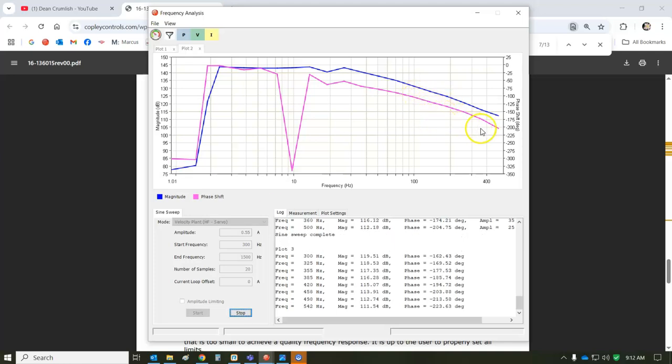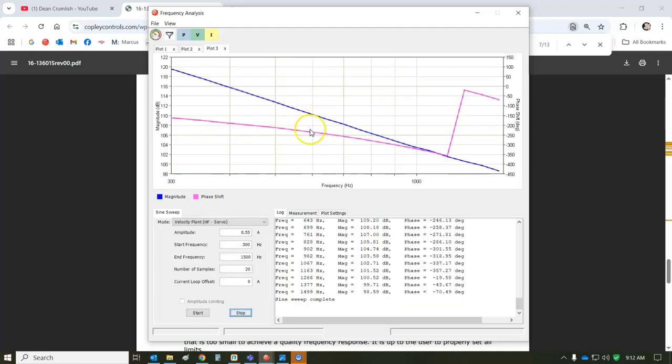So there must be a pole around 300 hertz. We know there's one in the velocity loop. I got some integral in there, so there's an integral break frequency that should carry my velocity out further. So that may be why I'm not rolling off. Well, it could be 20 dB per decade, so that does appear to be so. But this is the plant, velocity plant. Okay, so we can see the roll off and the phase shifting, and then this is just a wrap. It doesn't really jump up this way; it just continues down further on. It's just a way to plot with a wrap.